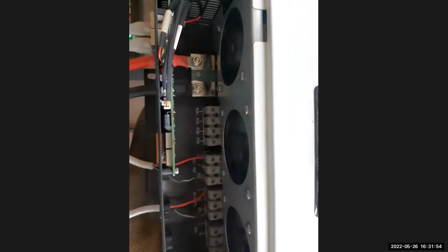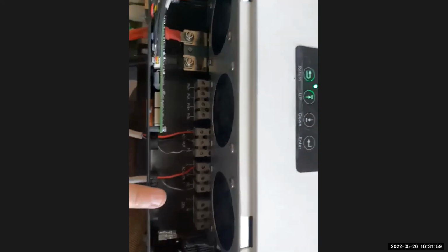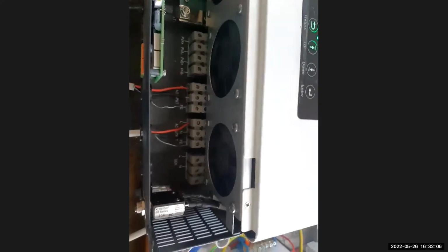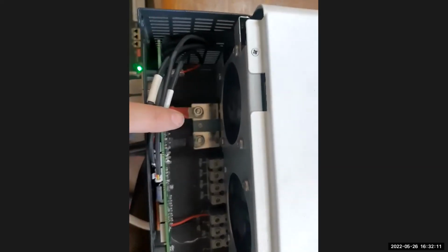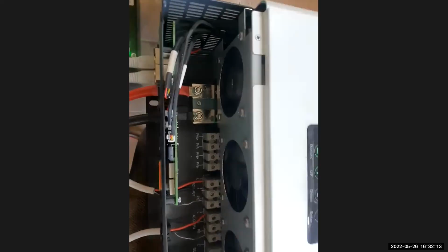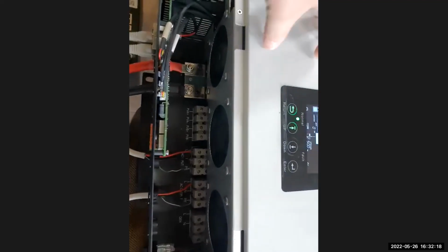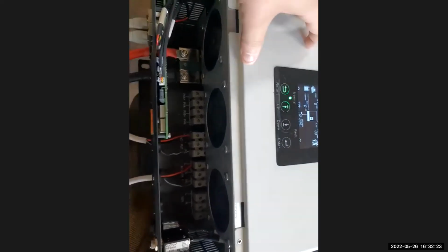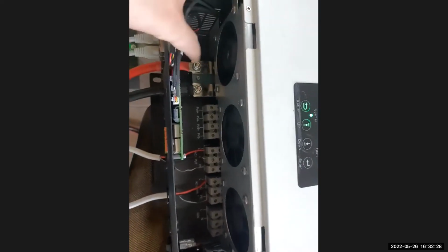From here on, you'll see that we have our input line and our output line, and our input line and output line are shared between the two inverters. As well as a battery connection from the one inverter and then a battery connection from the other inverter. So you must see these two inverters as their own installation, if I can put it like this. This inverter has its own input and output breakers. I'll go through that box as well with you, and its own input of the battery.